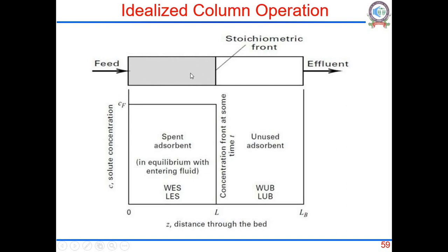This part of the bed is completely saturated with the solute. No longer is adsorption happening here. The feed is simply coming through here, and this is where the adsorption starts happening. Adsorption or ion exchange starts to happen, and the remaining part of the bed has still not seen any ions or any solute. So this ion exchange resin or the adsorbent is still in the free form. It has still not adsorbed anything. So you can idealize the situation. You can think about this as an adsorption front.